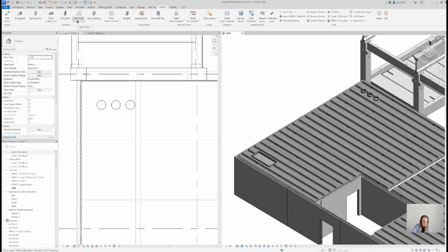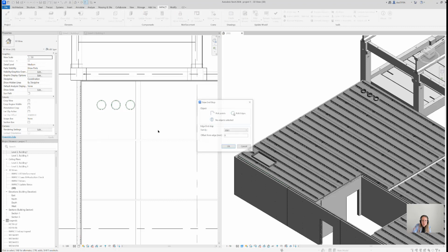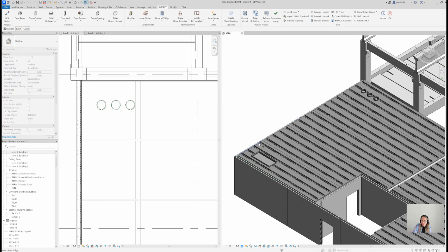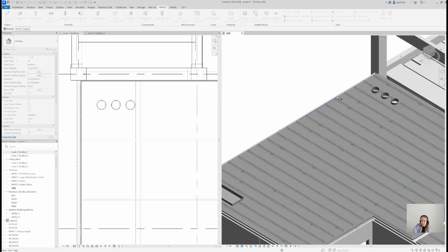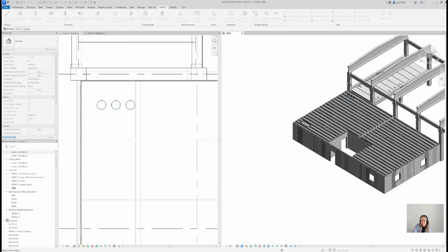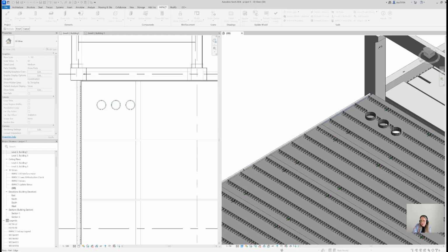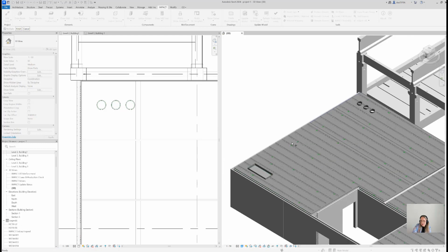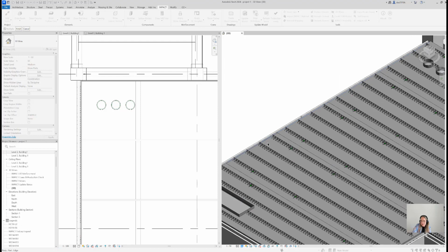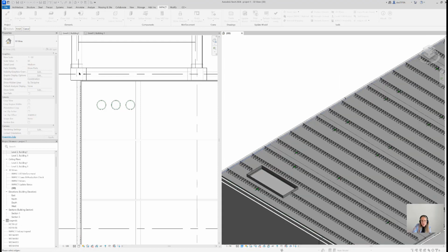Now, as we're going further in time, I want to just demonstrate the end stop, the edge end stop. We have this functionality where you can say draw end stop and you can just pick the edges of the element. So if you want to have end stop on all this side, you can just pick the edges of the elements like this and say finish.